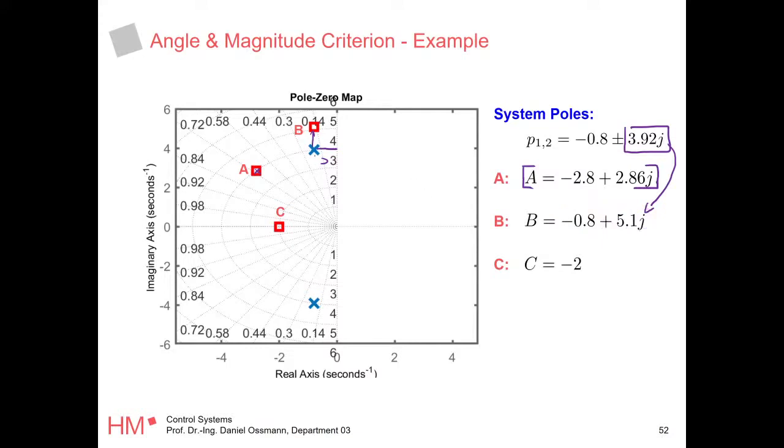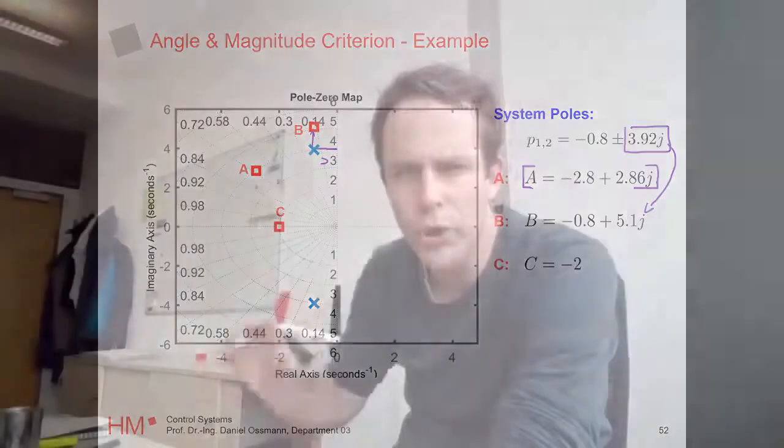And finally, we want to increase the damping further, and we know that this guy moves down, and probably we want to have some pole here at -2, because this guy will be slower. A position of -2 means a time constant of 0.5. So actually we are making our system a little bit slower. Okay.